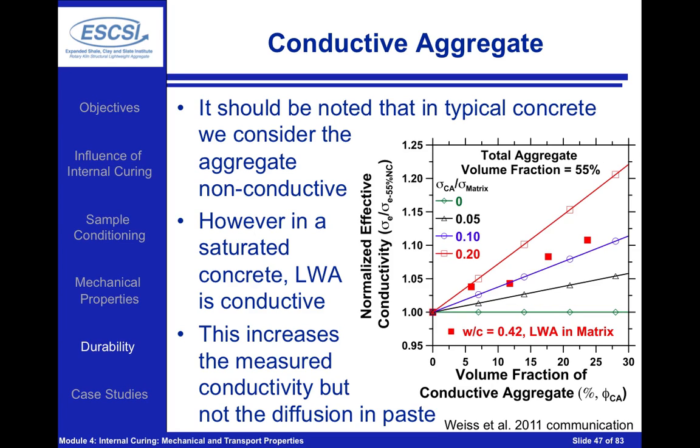This is because the aggregates themselves are going to conduct in the system, and you're not just measuring the paste properties. If this is a question that arises, we'd be happy to help you do the calculations to figure out how to account for the conductive aggregates.